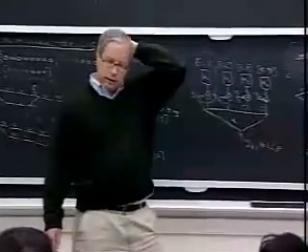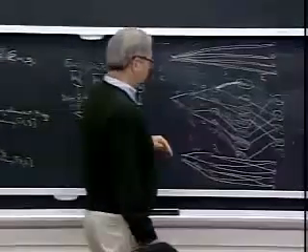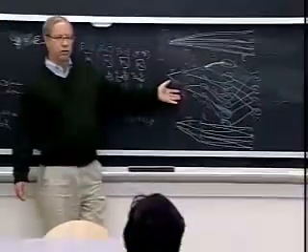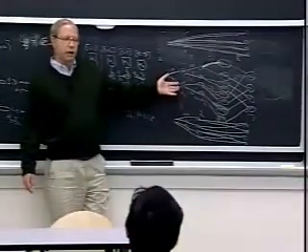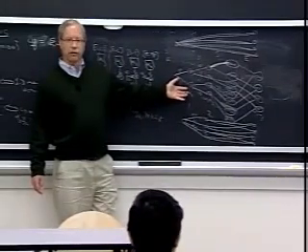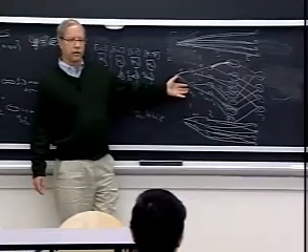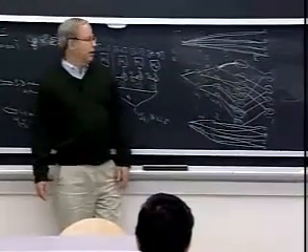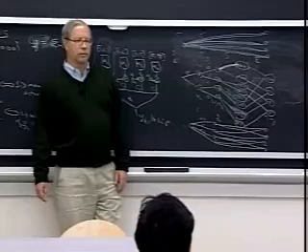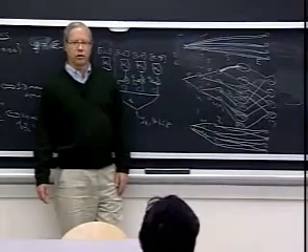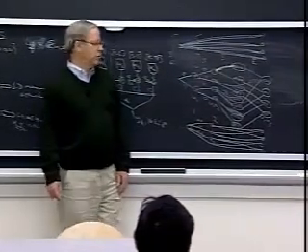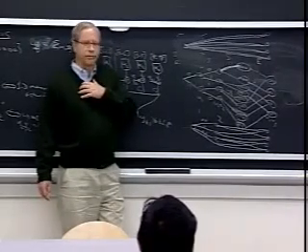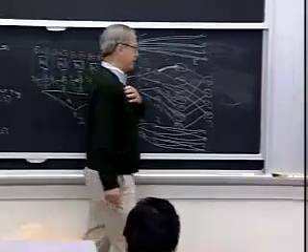Okay, so the good news was that with the Viterbi algorithm and a minimal trellis, we can get a simpler, optimum, maximum likelihood decoding algorithm for block code, simpler than exhaustive decoding. The bad news is that under this assumption, the complexity of that algorithm is still going to go up exponentially with n, maybe just a lower exponent, that's all. All right, so we haven't really solved our basic problem, which is exponential decoding complexity, by going to trellis decoding.